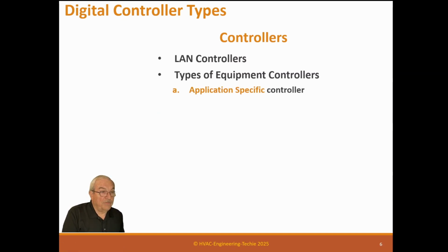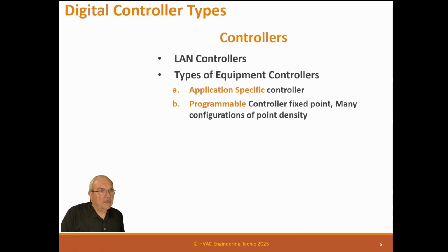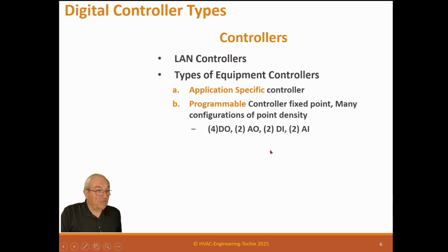They do need to be configured, but they're already programmed. A programmable controller, fixed point. They've got a certain number of points on them. Many configurable or point density. Many configurations of that. Like you might have one that's 4 DO, 2 AO, 2 DI, and 2 AI to run a small fan coil